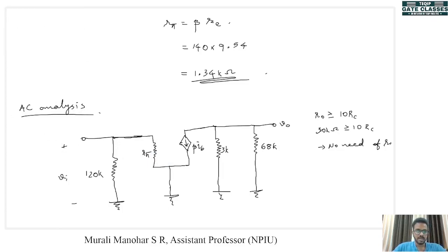So I can redraw this circuit. I can split it into two because this point is connected to ground and this point is connected to ground. So I will split that. This is connected to ground. This is also connected to ground. This is base and across here we have VBE. Okay. Now when you look from here, this is VI, this is II. So we have ZI here. This is V out and I out will be flowing like this. So here we have Z out.